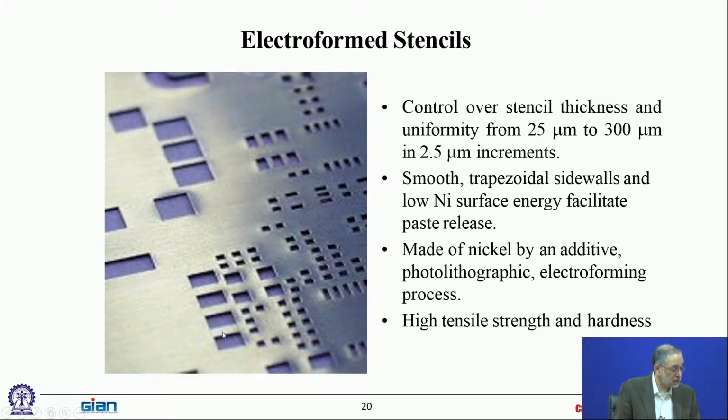The thickness of the stencil is very carefully controlled because that's how much paste you're putting down. So you want a metered amount of paste. You don't want too little, you don't want too much. You want just the right amount of paste. So the thickness and the size of these stencil openings is an entire art in itself. Well, science and art, okay? So a lot goes into designing stencils right. And if your stencil is not right, you're not going to get good solder joints.